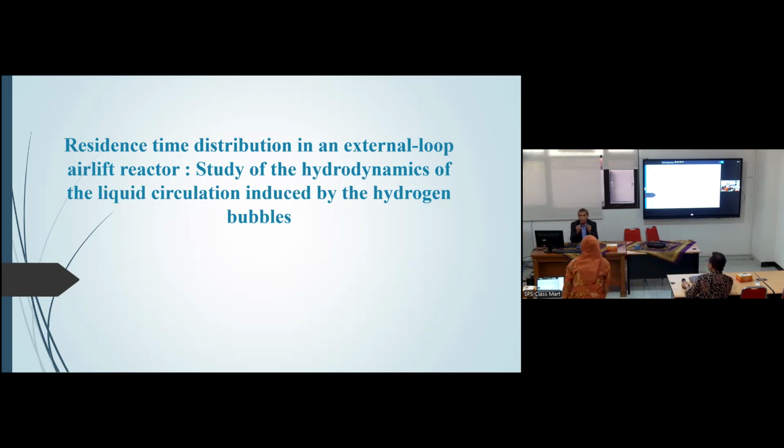Yes, yes. The scale up is easy, because I work with semi-pilot and pilot scale. I can reach, for example, 150 liters to treat as a batch reactor, and I can use a continuous reactor. The flow is continuous in this reactor, for example, which is almost industrial. It's a pilot scale, and I can scale up. It's possible to scale up.